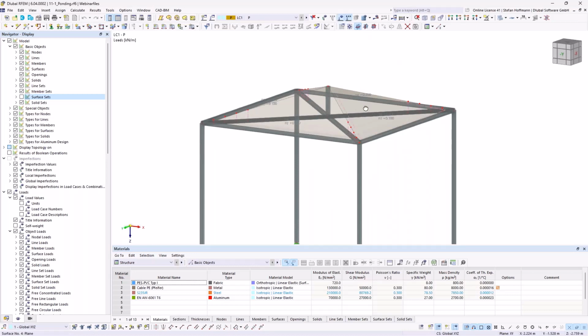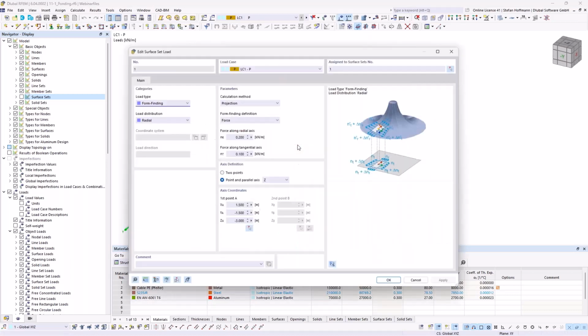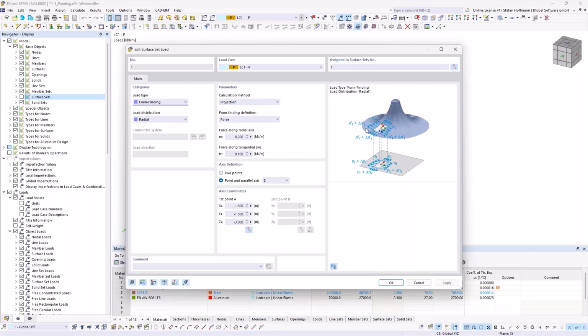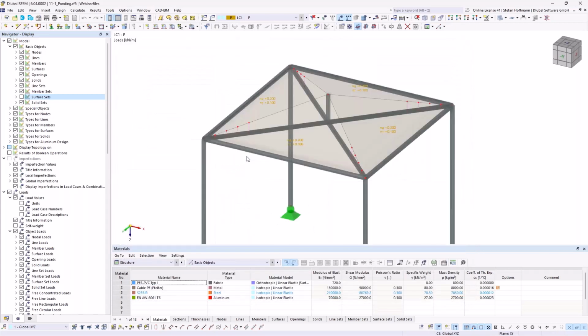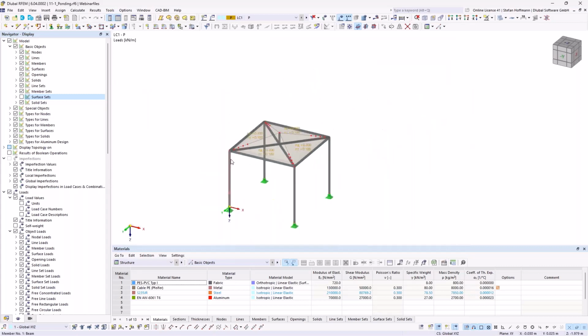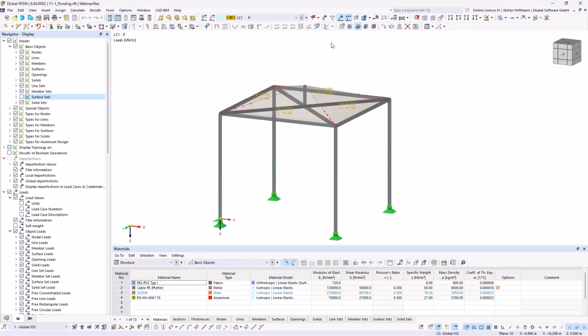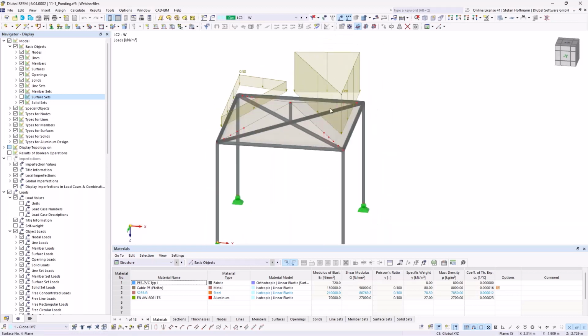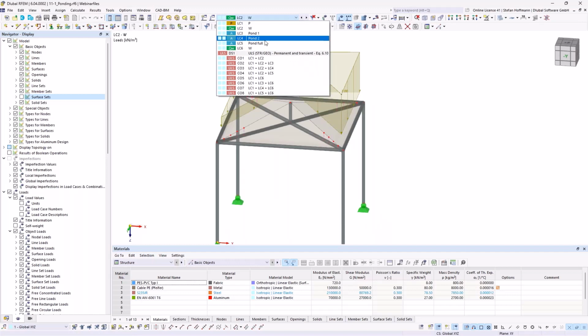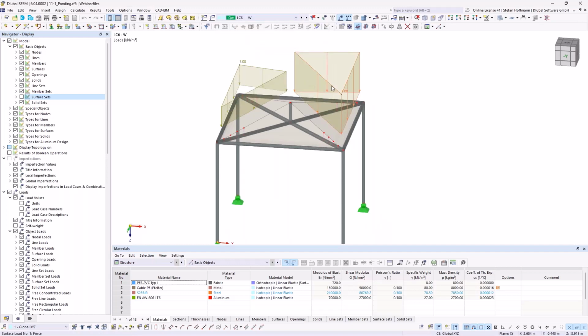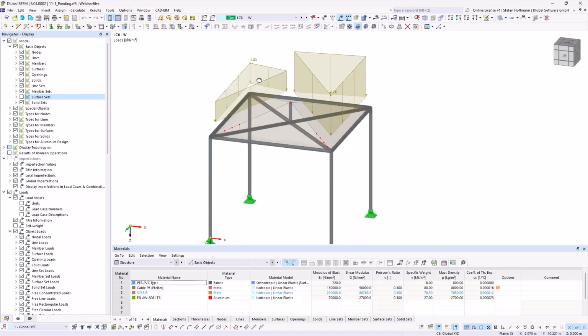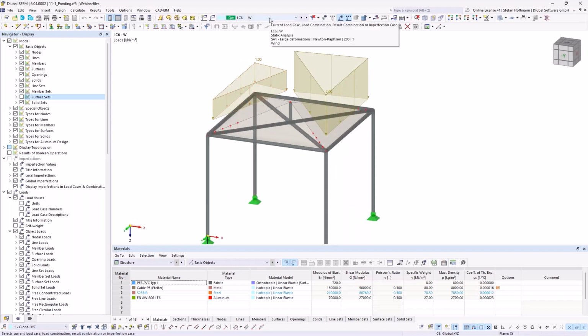I'm just putting a normal pre-stress on my membrane. I use the projection method because I want to reach such a tent shape where I enter some imaginary values. They may not be practical values, but the pre-stress will not be that high, because usually you will also have some cables tensioning this small tent. And then I will load my tent once with such an imaginary wind load, so a high load on one side, a quarter on the other side, and also a high load on this side and just a half normal pressure on my surface on this side.